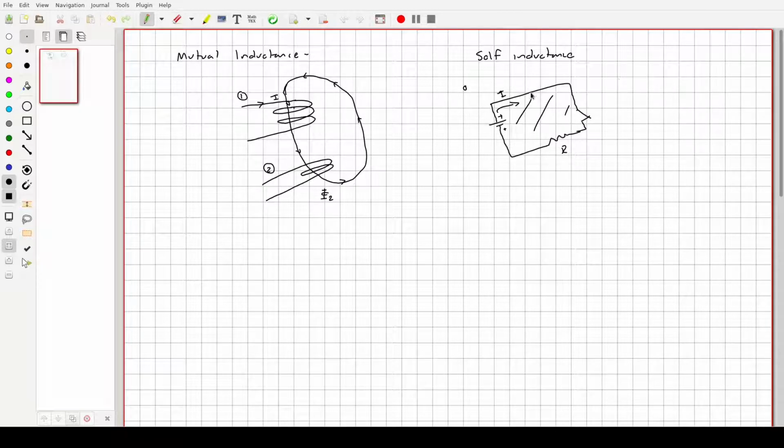So here, for example, we know, using the right-hand rule, that you would have magnetic field changing in this direction right here. And so what's created, as a consequence of this changing flux, is an oppositional current that goes back like this. Okay. So what that does is to actually take away a little bit from the current that's building, so it prolongs it. It causes a bit of a lag with respect to that. So what's happening here is this is doing it to itself. So that would be an example of self-inductance.